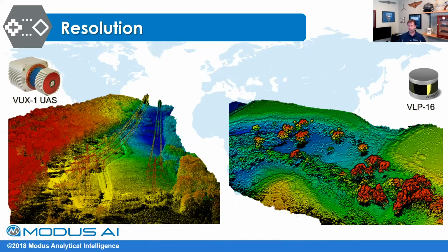On the other hand, for the VLP, we're still getting roughly the same amount of point density per meter squared. But if you're doing topography or you're doing open area vegetation management, you can still get a lot of data out of this. And that's why most people actually still buy a Velodyne, because it's affordable and you're still getting great data. So when I sit down with a customer and I'm having this discussion, I'm really going into what their specific data needs are and what they're going to generate as a product, to judge which product makes the most sense.